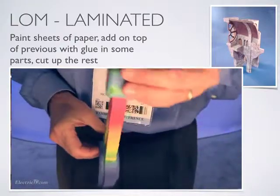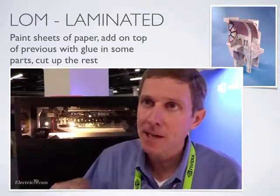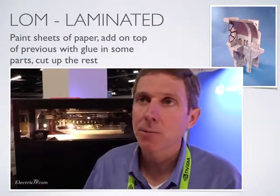And the reason why we use a special ink that goes through the paper is because you need full color density on the model. So if you didn't have ink through the paper, the sides of the parts would be white. So we need to get full color on the tops, bottoms, and sides of the parts.